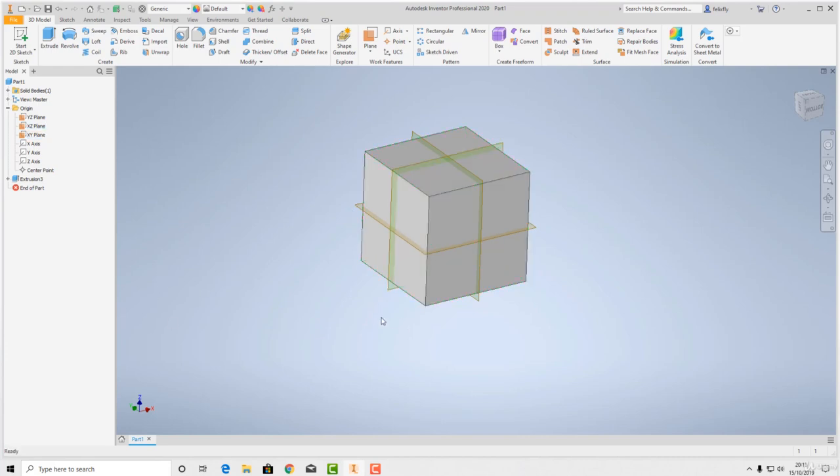So I'm going to say, out of the side of this cube, we want a cylindrical shape protruding out the side of this cube. Okay. So because it's on this face, when you look at it, you would say, which face is this feature protruding from? So we're going to click on Sketch, and we're going to do a sketch on this face here. So you can put a sketch on a plane, as we did, or on a face of an existing feature.